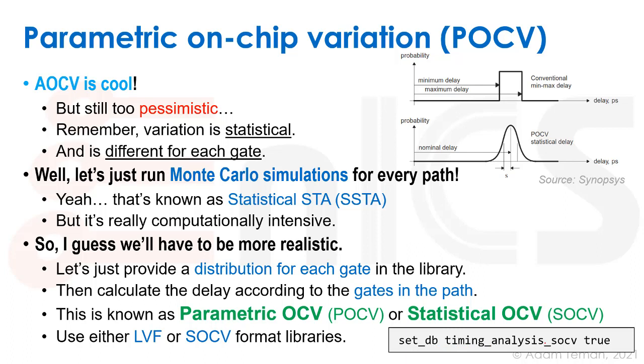are a lot of nooks and crannies that you have to go into and look and fine tune when you set this up. But really, when you go back down into sign-off timing, you should nowadays, in the state-of-the-art type of scaled processes, use these POCV or these SOCV libraries and timing to reduce a lot of that pessimism that we took with standard OCV.